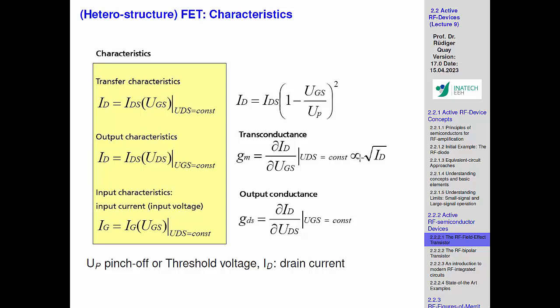You see it's increasing, not linear, but at least when we have a higher current, we also get a little bit more transconductance. That's very simple. That's not rocket science. It's true for every transistor in this universe. It just says that the transconductance increases, among other things, with the absolute current level you are in. So this gives you some guidance.